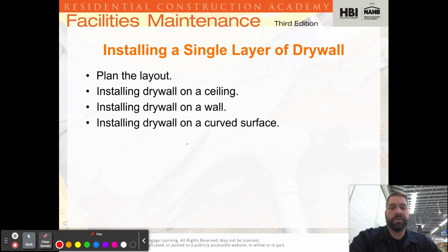So if you're going to install a single layer of drywall, always plan the layout, right? And that's why you always do a drawing first, to get an idea of the wall, the centers of your studs, the locations of them. When you're installing drywall on a ceiling, there's a few ways to do this. We will cover it in lab. This is why you will be working in teams.